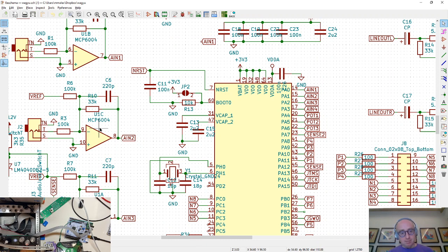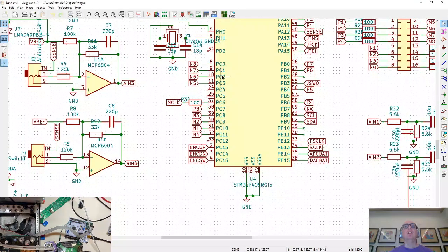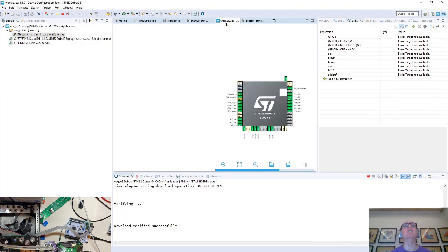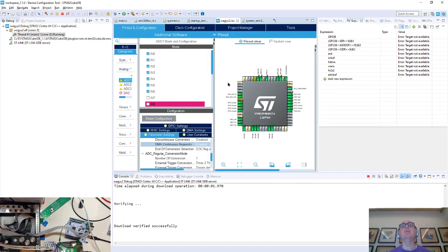Let's do the encoder, because that's easy. I have forgotten what pin the encoder's on. Here it is: up, down, and switch. And it allows me to show you pin interrupts as well. So the switch we're just going to do as a standard input, and up and down, so 2 and 3 are going to be interrupts. Oh, right then, easy. Pin 2.